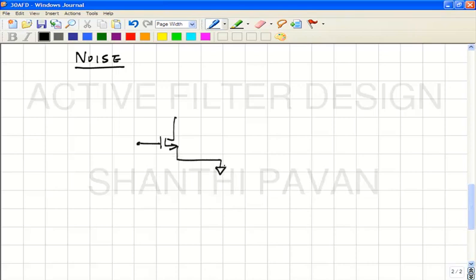circuit of the differential pair, and please note that even if there is a tail current source, as far as differential signals are concerned, that source coupled node is ground, correct? And this is coming from where? This is coming from the error amp, and what is the error amp output for differential signals?